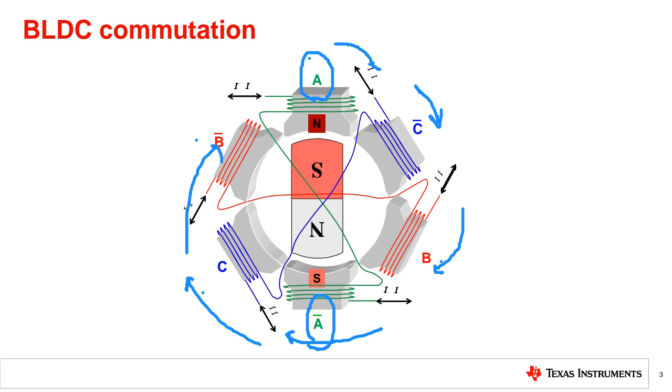Using a Hall sensor. A Hall sensor is a Hall effect position sensor. If it detects a magnet pole, it gives a flag as a binary 1, for example. If you are in the A phase, it will generate 100, for example. If you are in the B phase, it will generate 010, for example. Every 60 degrees, it generates a flag as a 1.